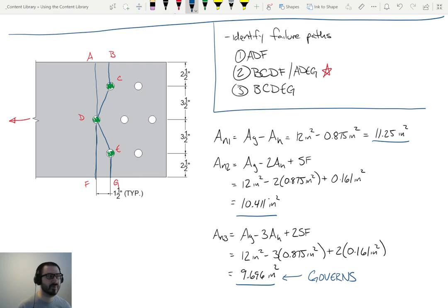So as an example, if you remember the very first homework assignment, you were given some loads and you had to plug them into load combinations to get the worst case scenario. And on that assignment, you reported the maximum load. And I believe it was from load combination 2. In that homework assignment, load combination 2 governed because it was the one that yielded the highest load.